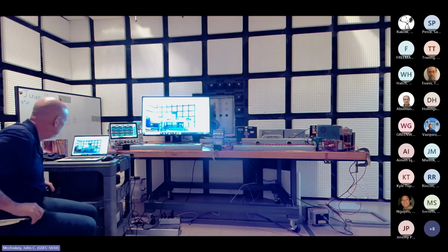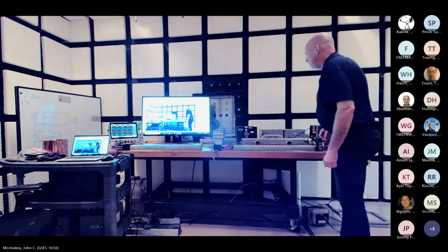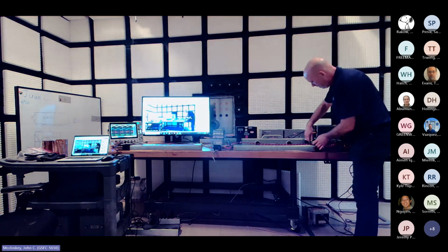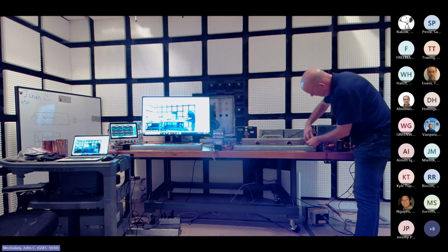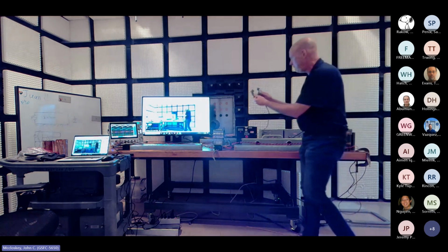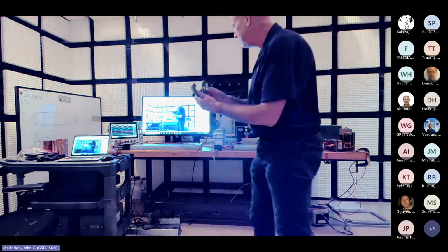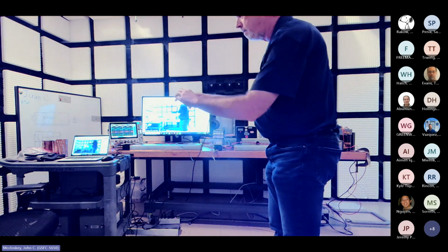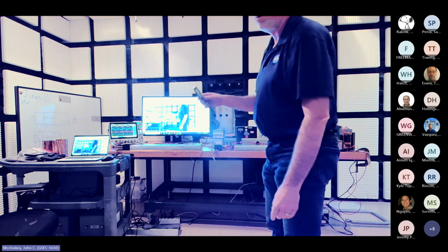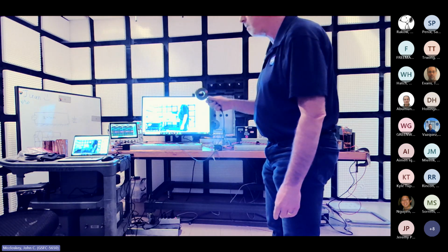Oh, I'll show you one more quick thing while I have the camera enabled. One of the last points there of how quick and easy it is to make these measurements. You know, again, these are clamp-on current probes. If you're not familiar with these, just as the name says, clamp on, right? And open it up. So closer to the camera here. It just opens up, clamp it around the cable, clamp it shut. Make your measurement. It really is very quick and easy to use these, and I can't recommend it highly enough that you do this early and often.